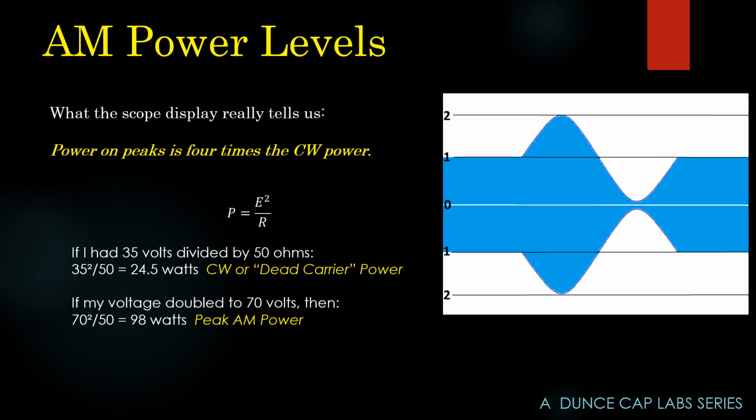If you had a 100 watt AM carrier and tried to modulate it, all you would get would be the downward peaks. Your watt meter would show a reduction in power on voice, which you don't want to see, and your audio quality would be absolutely horrible.